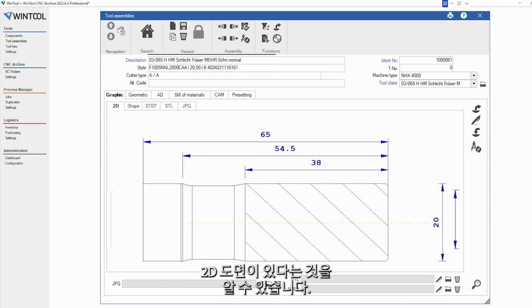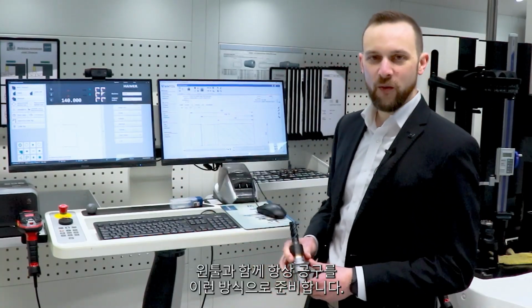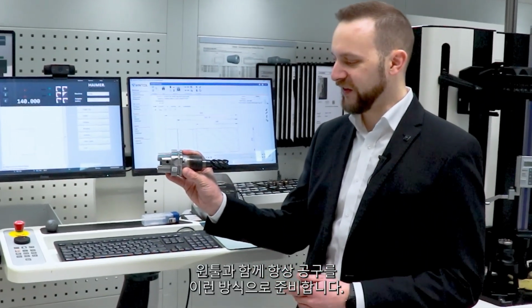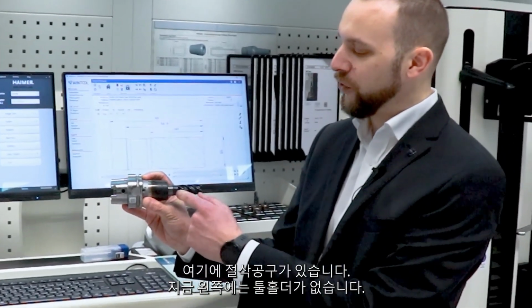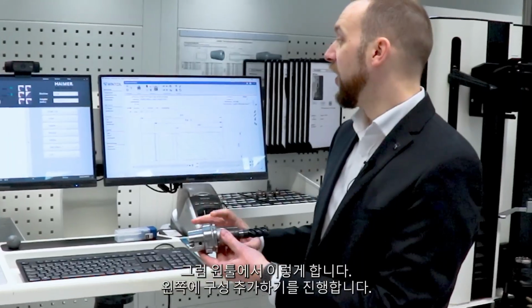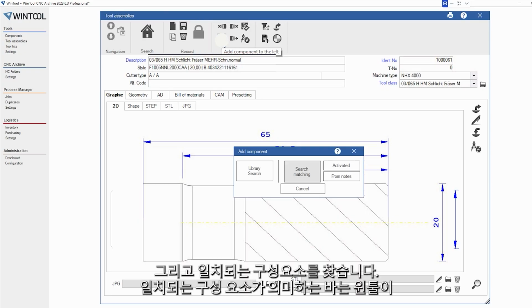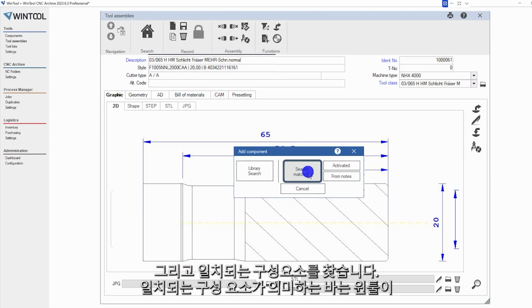And now you already see that we already have a 2D drawing of the cutting tools. And WinTool always places the tool like this. That means here's the cutting tool, and now on the left side we are missing the tool holder. So I say to WinTool, please add a component on the left side, and please find a matching component.